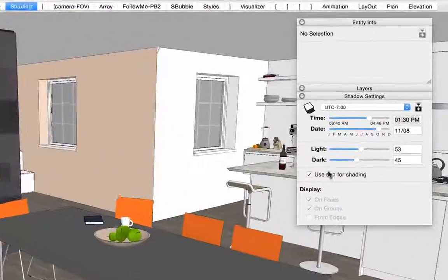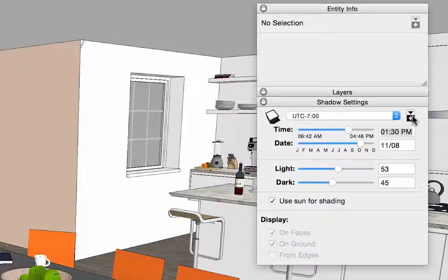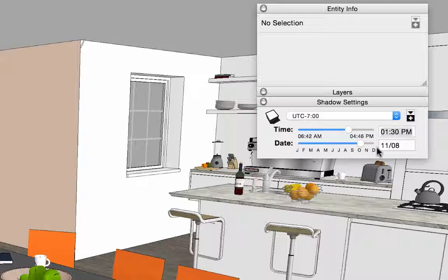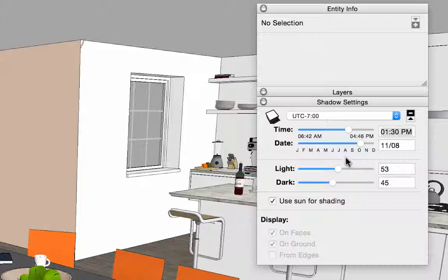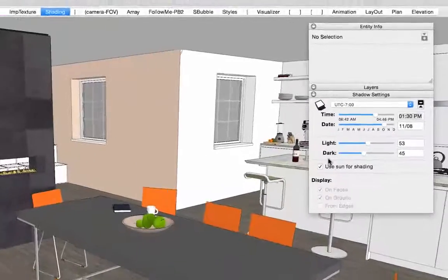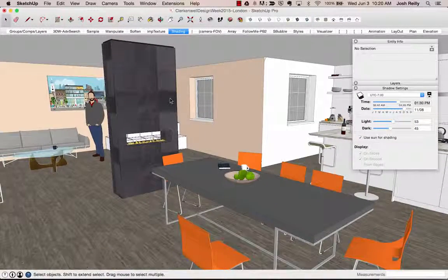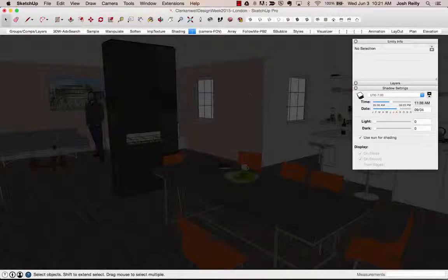And if you don't see all these options, keep in mind that this little button here can expand certain boxes in SketchUp. So don't forget that you may be able to expand it if you don't see what you're looking for there. So this is important because in SketchUp, with interior spaces like this, there's actually a lot of control you have over the shade value. And a lot of beginners don't even deal with this. They kind of just go along with whatever's preset there. And your model can look very dark, kind of like this, if you don't pay attention to that.